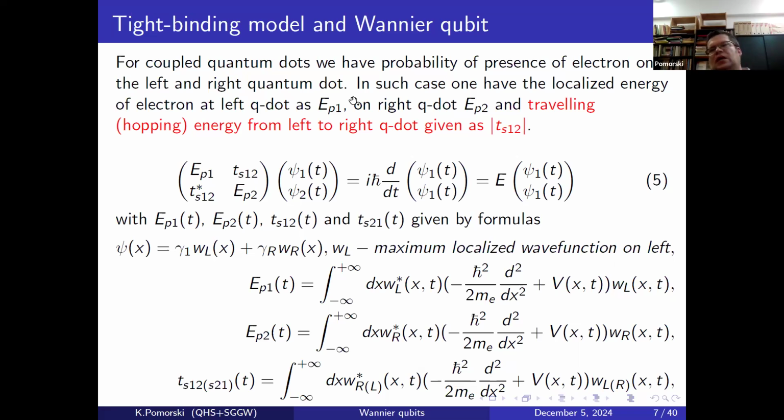This electronics has certain limitations, as I mentioned 1 week ago, simply because the size of a Josephson junction is not so small. Technically speaking, it's a mesoscopic system. It's not a fully nanoscale system. It's on the boundary between the nanoworld and the macroscopic world. This is due to the size of the Cooper pair, which is quite big, in low temperature BCS superconductors currently used, in the range of 300 nanometers.